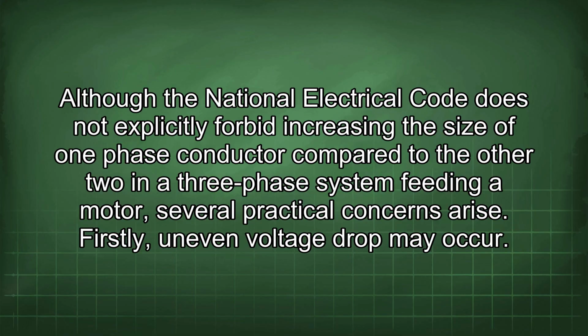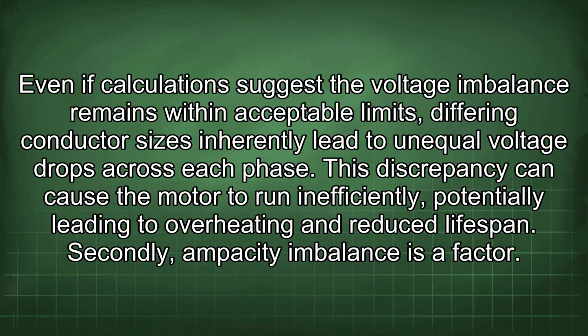Firstly, uneven voltage drop may occur. Even if calculations suggest the voltage imbalance remains within acceptable limits, differing conductor sizes inherently lead to unequal voltage drops across each phase. This discrepancy can cause the motor to run inefficiently, potentially leading to overheating and reduced lifespan.